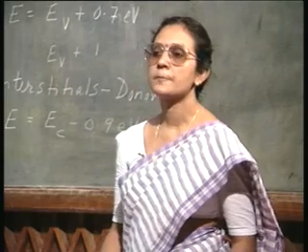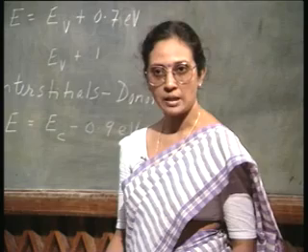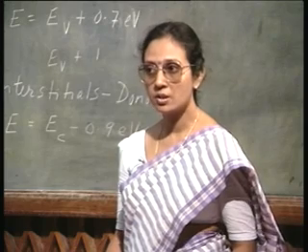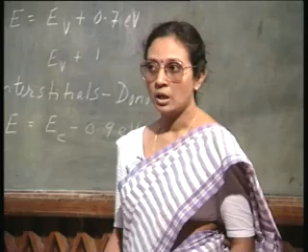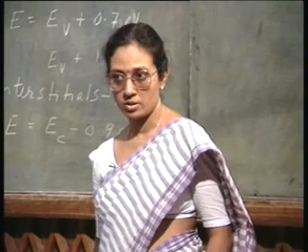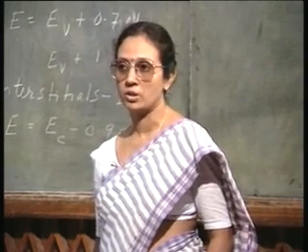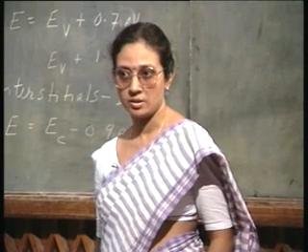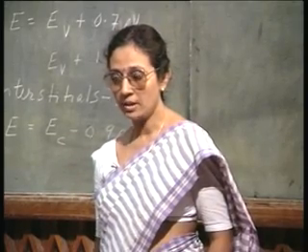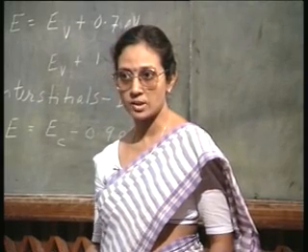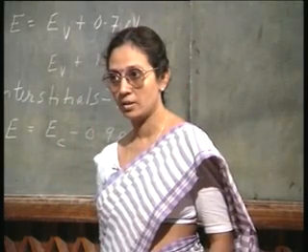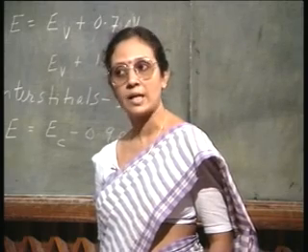See, in the growth process, silicon is first molten and then it is solidified in a controlled manner, so that the growth is only in a particular crystal orientation. Now, silicon is a material which expands on solidification. So, if during solidification any part of the melt is constrained, by the wall of the container for example, then when the material is trying to expand but cannot because it is constricted, there will be a lot of stress on the material. So, this is a time when dislocations can form.